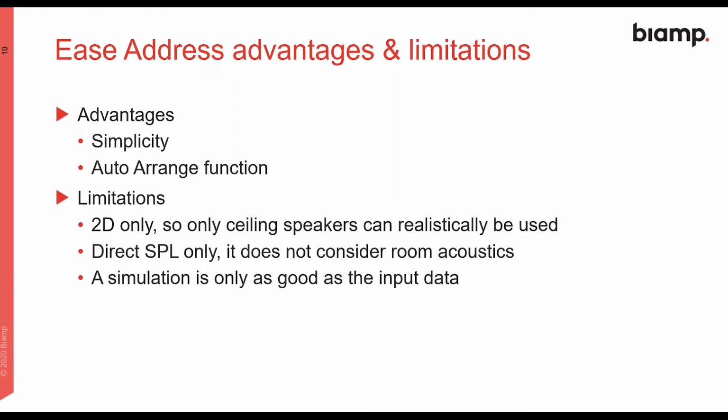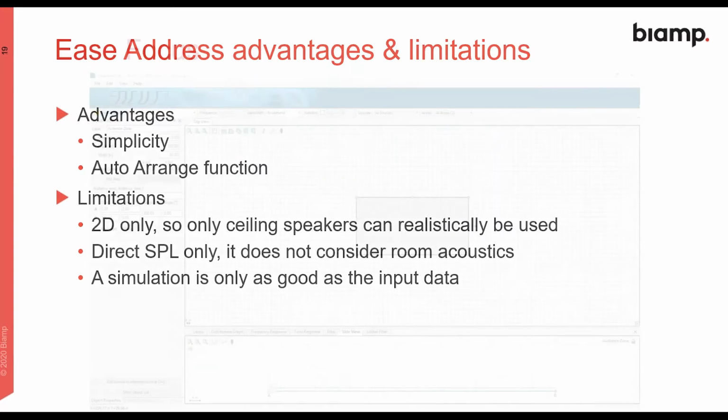The limitations are, as I said, it's 2-dimensional only, so only ceiling speakers can realistically be used. It also only concerns itself with direct SPL, so it doesn't consider room acoustics or room finishes in any way. And of course, the simulation is only as good as the input data that you put into it. But it does give you a very good starting point for simple conference rooms, for example, with just ceiling speakers.